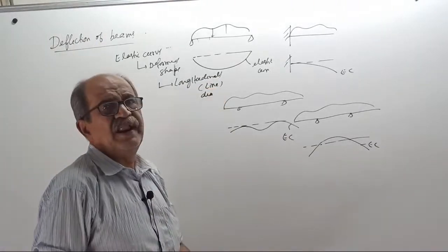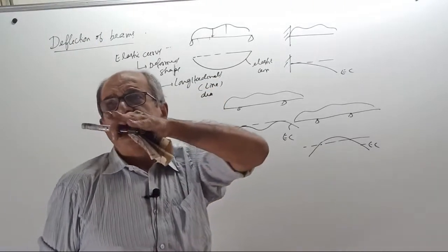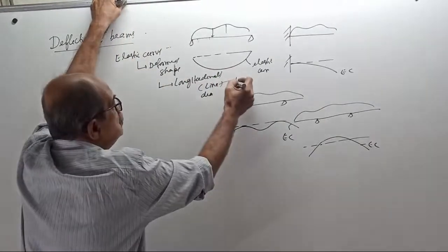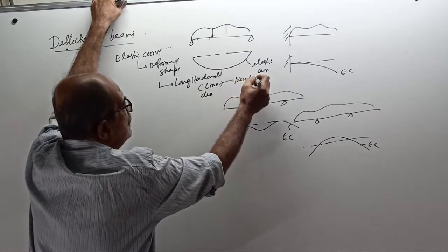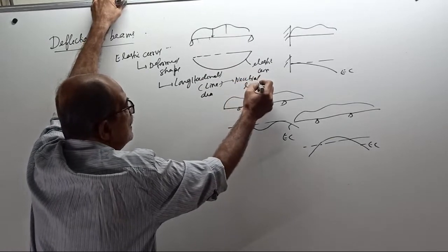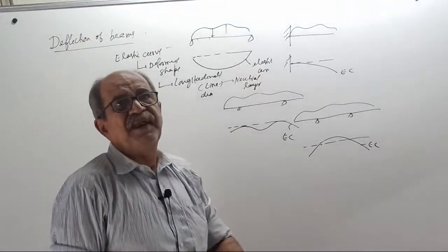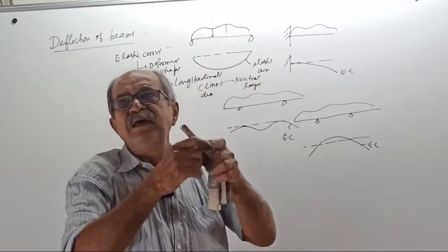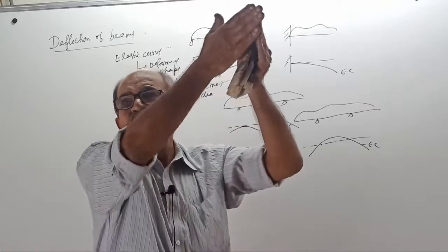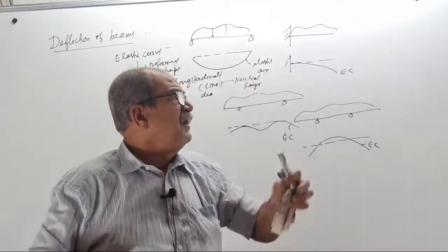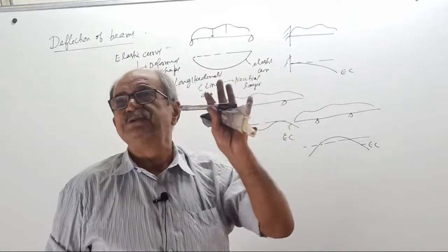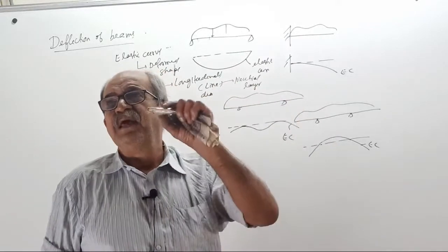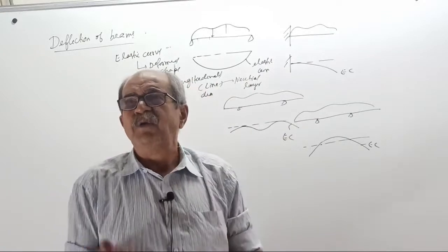Thickness we don't show there. So the deformed shape, that line diagram, that line corresponds to what? Neutral layer. Actually, if a beam deflects down this way, the neutral layer, how much deflection? Actually, the radius of curvature will be very huge. Therefore, the deformation for upper and lower will hardly matter.